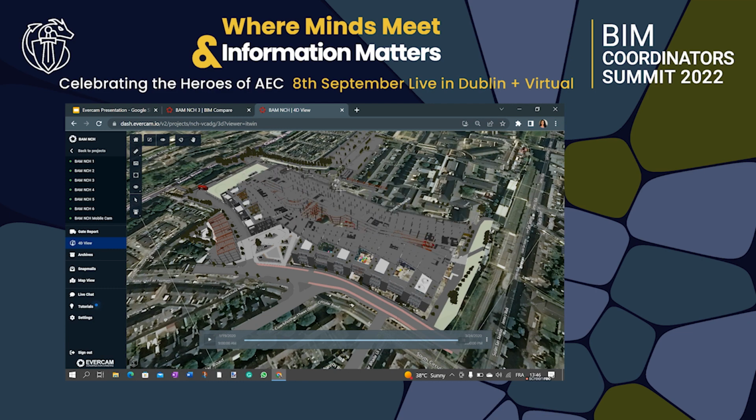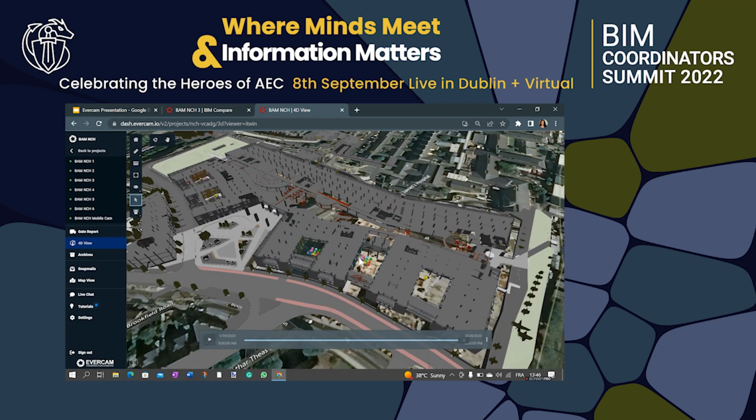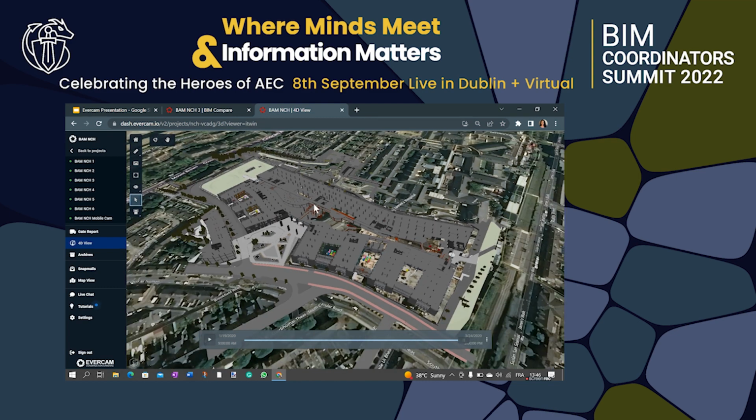So here I did a section. I can remove my sectioning plane and then zoom in, and I'll be able to see what's happening inside, structural details, furniture, and so on to better explore my BIM model.